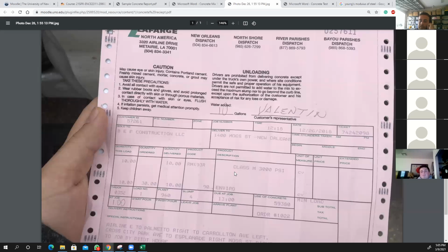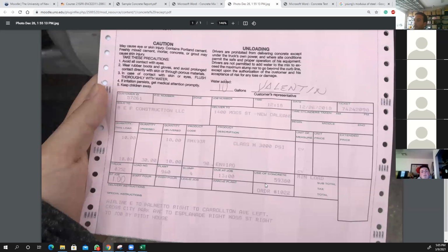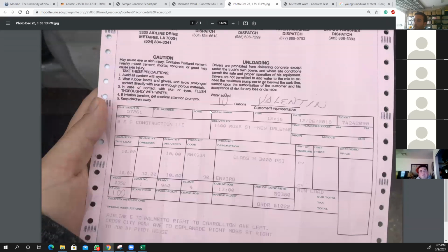receipt. And also you have the 3000 PSI strength on this concrete. You take your sample and then you get the testing done. It will take a few days to get the results, but still you have the right to compensate from the Lafarge or concrete company if there is something wrong with their receipt. That's what you do if you're on job site. So you do the slump test, check the time, and then take a sample.